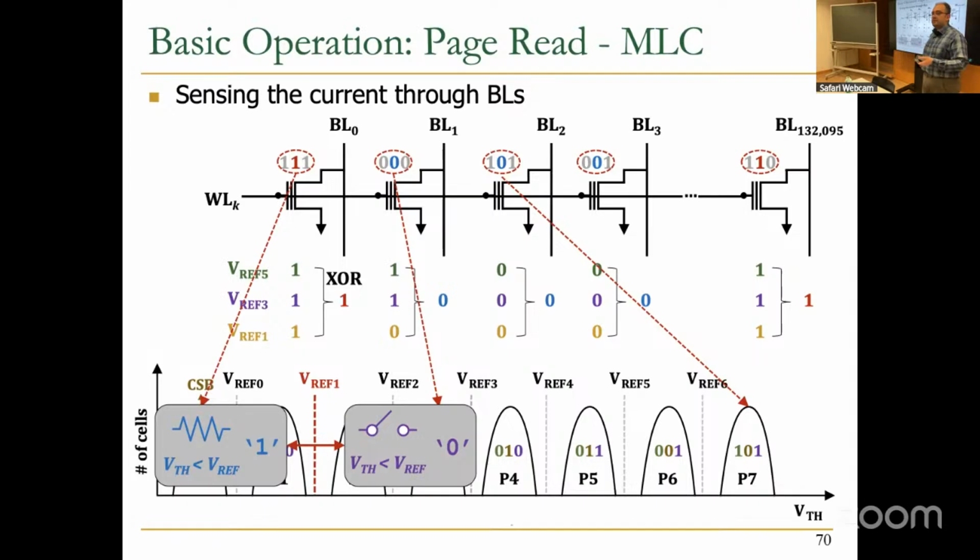I don't understand why we're reading from the center bit. It's just an example. Oh, okay. But normally you'd be reading all 3 bits. No, not normally, actually. Normally you read one of them because you want to read, for example, a page. So we are storing 3 pages, for example, in a word line, right? So you want to read the center page, for example. I thought it was always like you had 3 bits of the same string back to back. Usually it's not saving 3 different data types on the same line. Yeah, I mean that can also be the case, but usually people don't do that. People store multiple different pages in a TLC, for example.